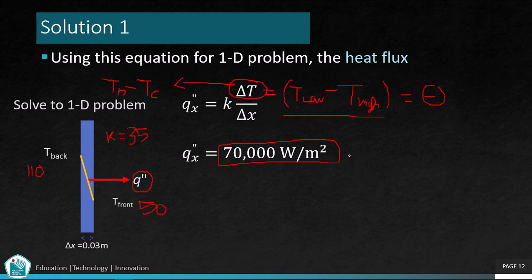Okay, to calculate the delta T, you don't have to convert into Kelvin, because even if for the delta T you use Celsius or Kelvin, the result will be the same. This is why it's easy for the delta T not to convert. But if we have a multiplication, you need to convert from Celsius into Kelvin.